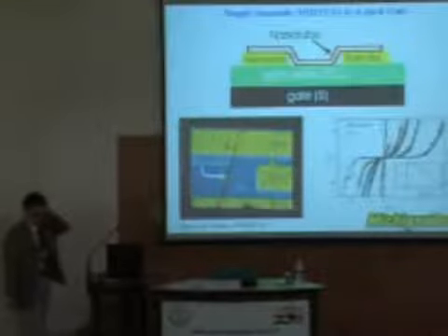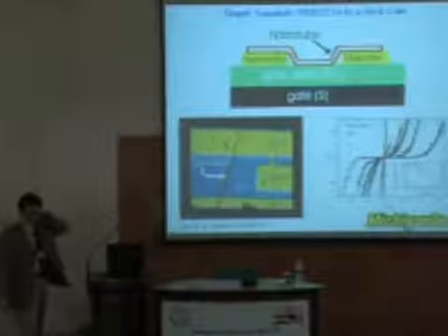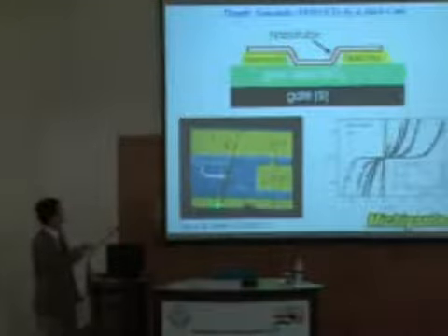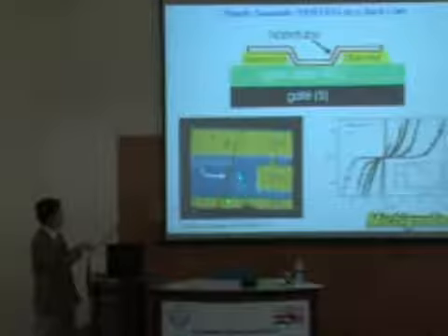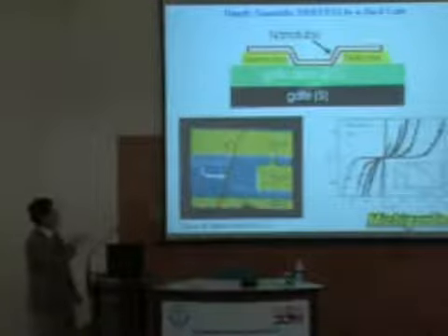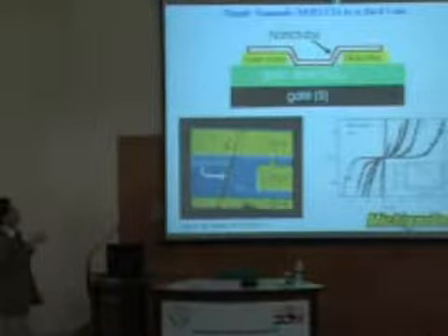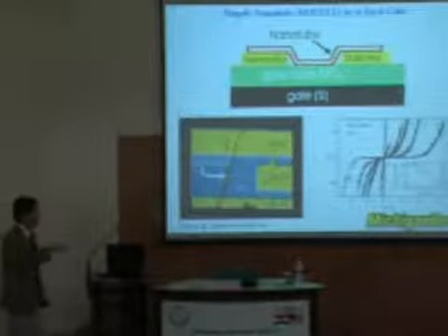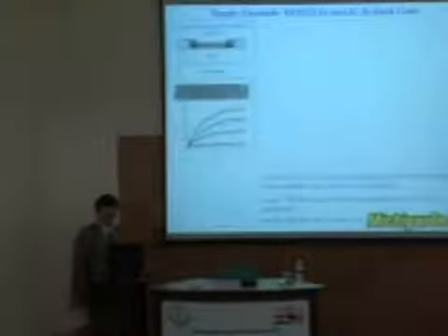This was the first field effect transistor ever made in the world, using a piece of single-wall carbon nanotube laying across 2 electrodes. The whole cross-section structure is shown here. Basically, it forms a transistor with source, drain, and gate electrode. You can see the switching is pretty nice.